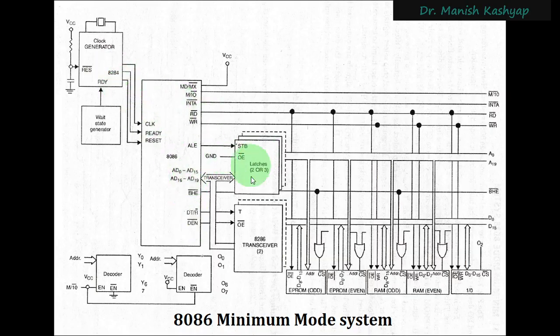Then after applying this clock, we had these latches, because we saw that in the T1 state of the timing diagram, we have to latch the addresses. Since the addresses in 8086 are 20 bits, we need three such latches here, because an individual latch has a capability of 8 bits or 1 byte. So we had these three latches, and 20 bits out of the available 24 bits of storing capacity will be used there. And then there was a transceiver. This was an optional device, but more or less it is used with this microprocessor, because it strengthens the signal that we have received from here. Since multiple devices are interfaced with this microprocessor, they can all draw their signal from this transceiver. Then we have odd and even memory banks of external memory connected, and then input output devices were there together with their address selection logic.